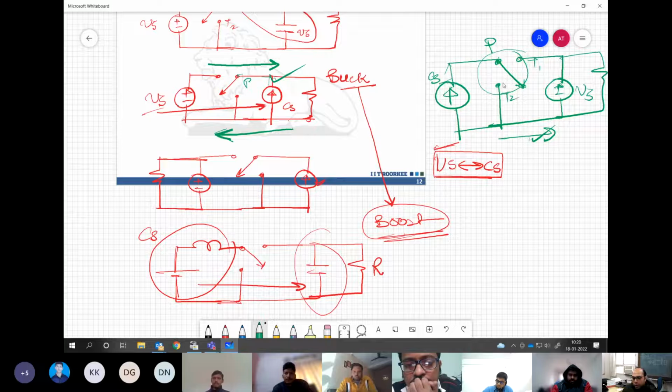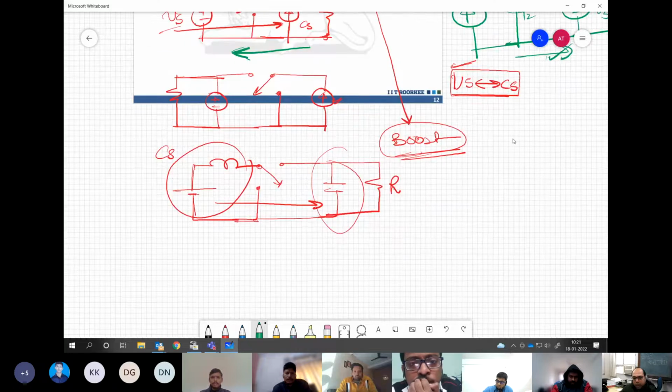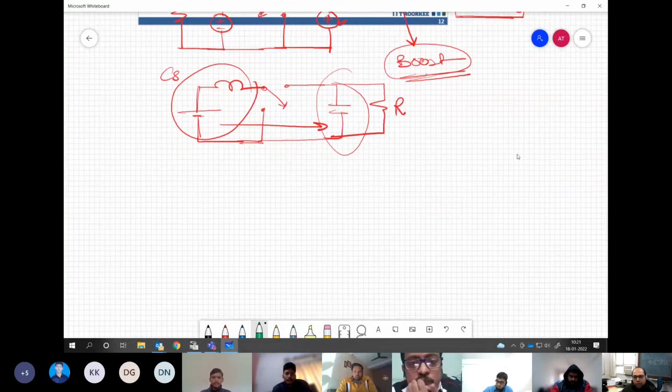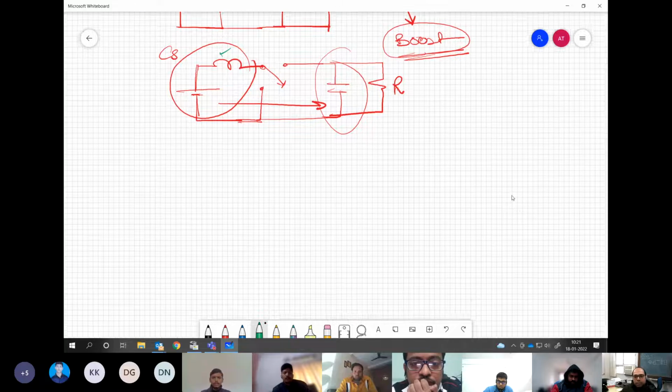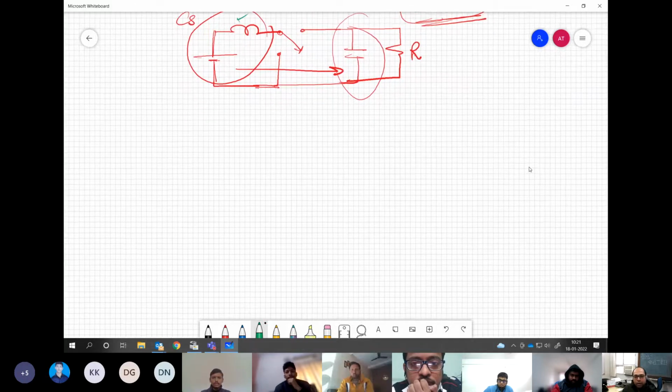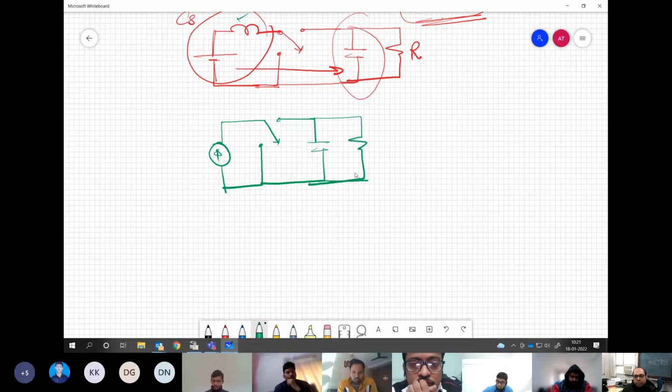Fine. Now with this, let us go to our next circuit. The way we realize our current source is we have a voltage source connected with a current stiff element. First let us see the ideal waveforms for this and how to derive the expressions. Let me draw this current source as it is, and we have a voltage stiff element, say a capacitor, and some load connected over here.